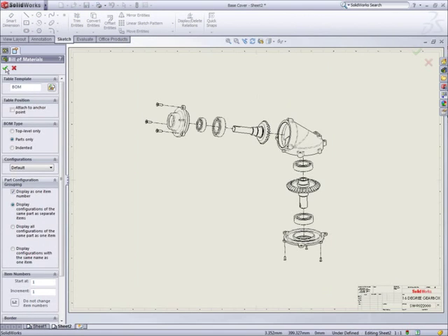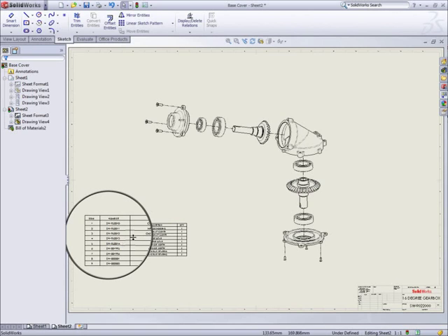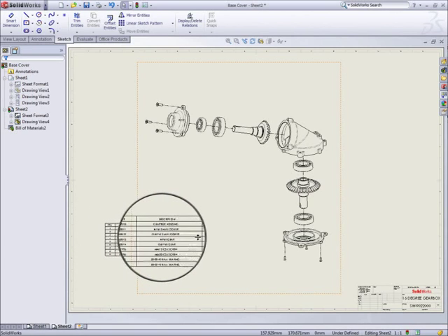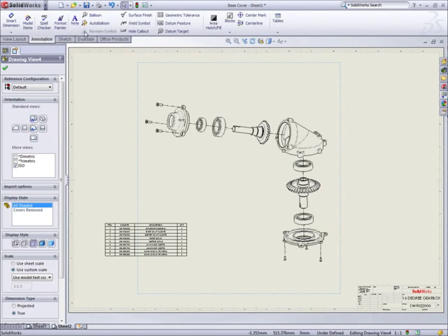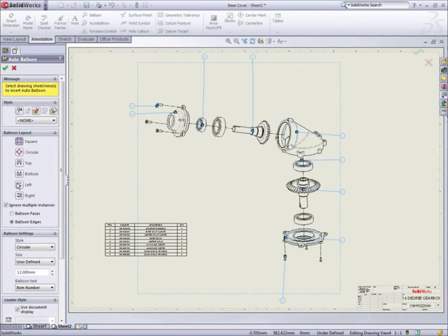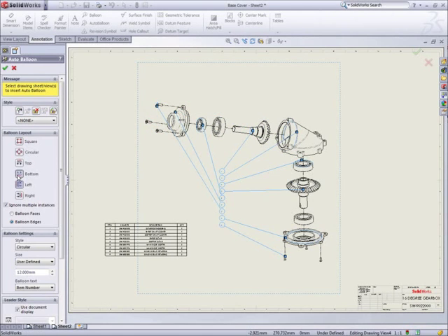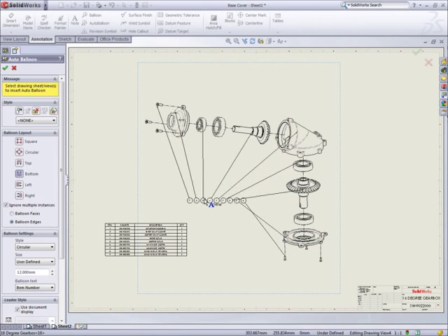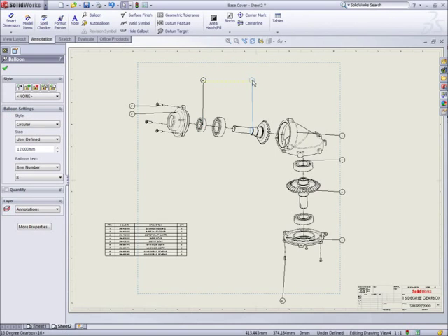The table can have as much or as little information as you want to show, with all the data taken directly from the individual part models. You can also edit this table, and like the title block, the information is written back to the model. For balloons, SolidWorks has yet another labour-saving device. Different layouts can be previewed, and as you move the balloons around, they resort themselves so that the leaders don't cross. A little tidying up, and the drawing is done, fast.